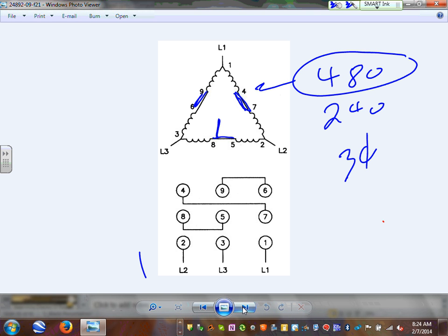High voltage, low voltage. They make motors with two voltages and two types, either delta or Y. Y is the more dominant. We know how they come, delta and Y, in shapes: three corners, 1, 2, 3 at the top, or a Y like this with one coil above it. Then the way you connect them, if you put the coils in series like this, can you see in series here? You get your high voltage.